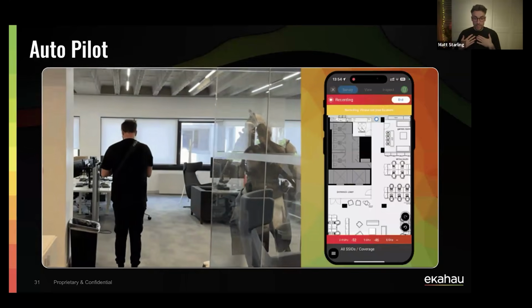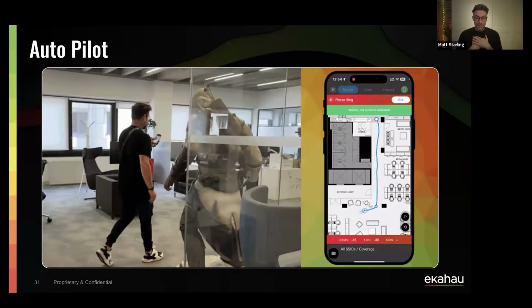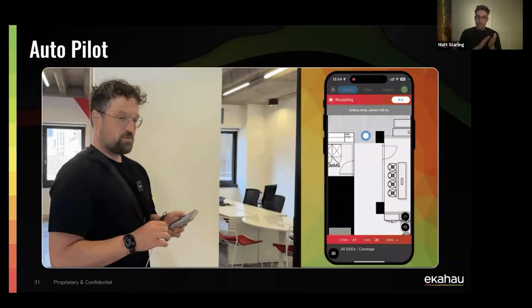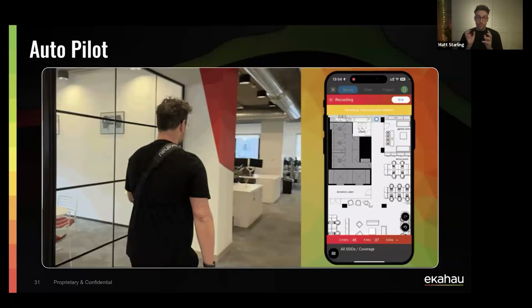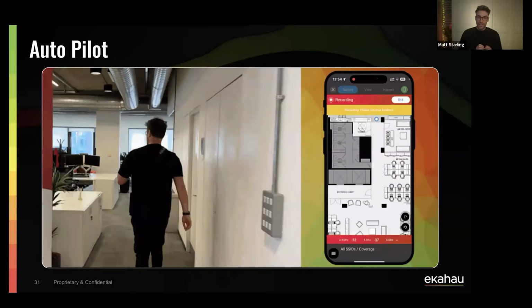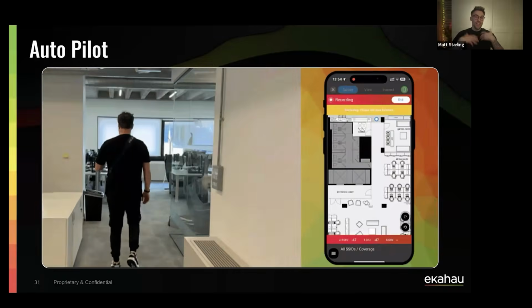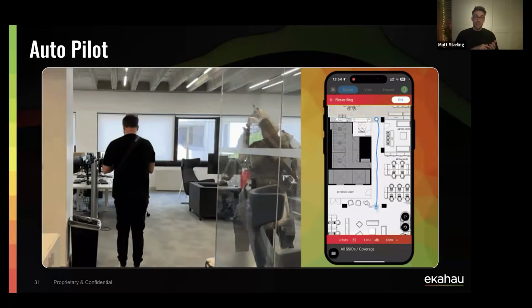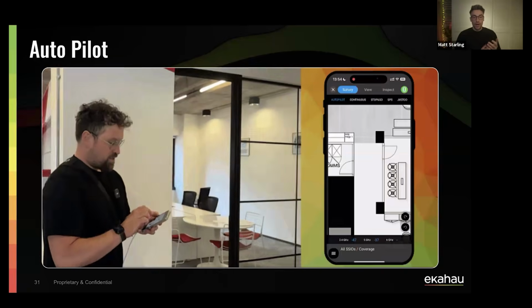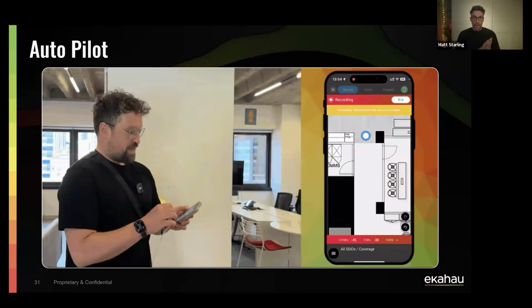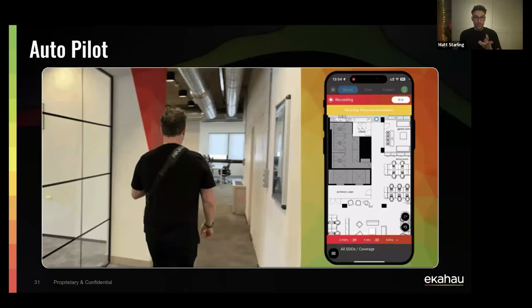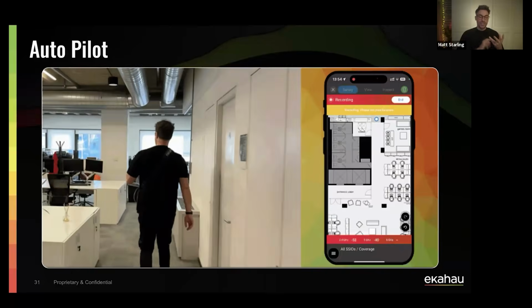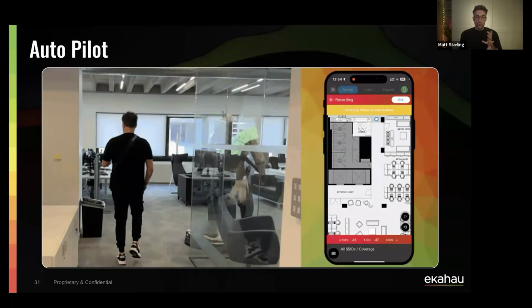And a tip here, and I'll admit I used to make this mistake: when you first tap your initial calibration point, the software says, hold on, I'm getting ready to calibrate your location before you start walking. And then you should start walking. What I used to do is tap and then start walking, and wonder why my path wouldn't be super accurate. So the tip is: tap, wait a second, then it'll tell you it's ready to start recording your next location, and then walk to a known reference point.